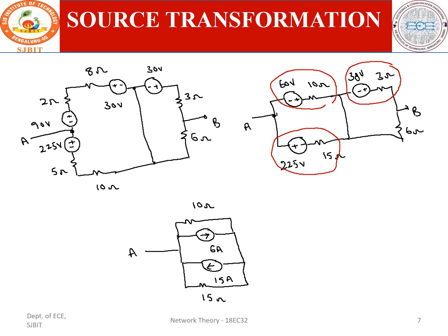Okay, again from this point, we converted this into current source, so we can write like this, and here there will be a resistance, it is 3 ohm, and this is I is equal to V by R. This is your 10 amps, and this is the 3 ohm. Another resistance is connected to this point and this, so we can write it is 6 ohm, and this is the point B. This is our 6 ohm.